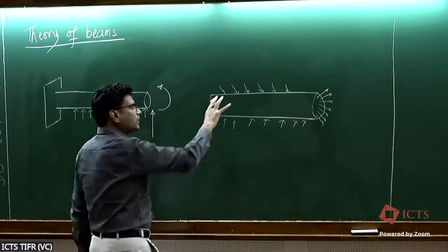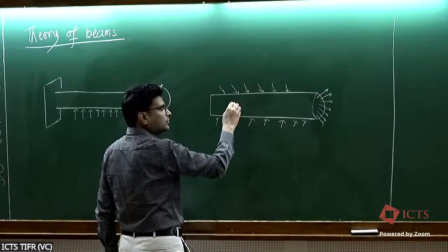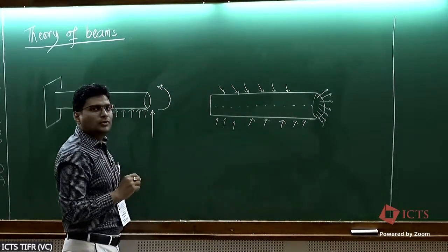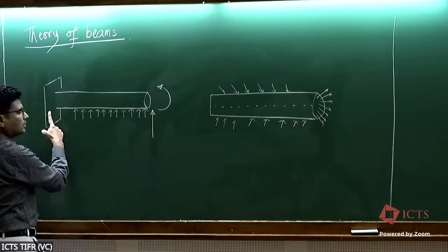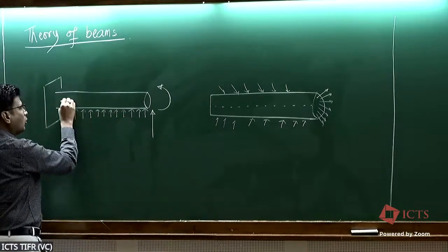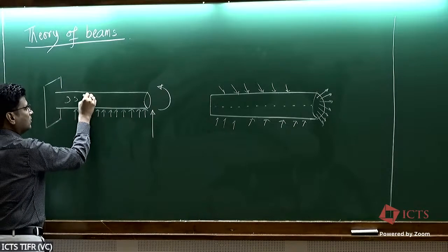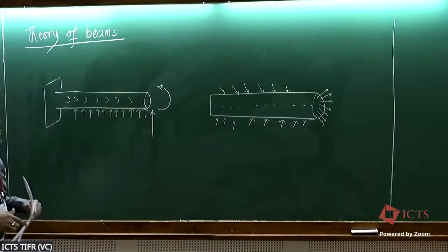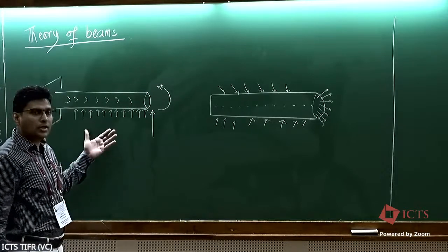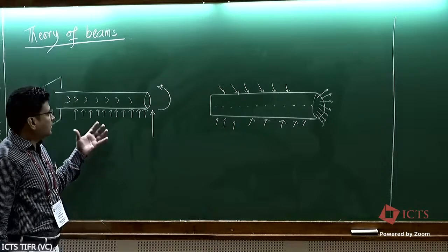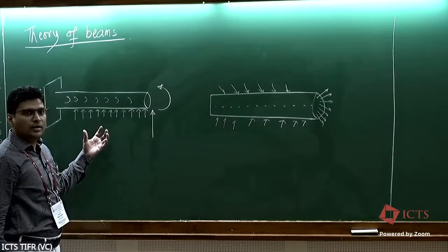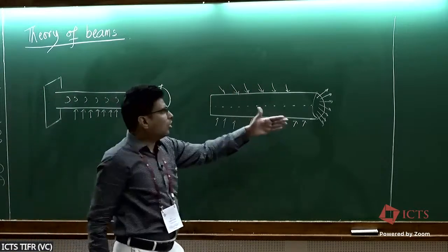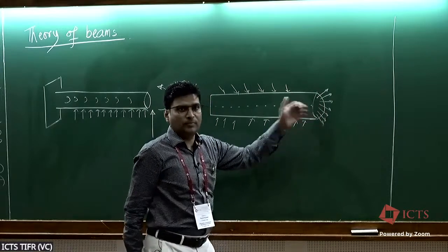And when you transfer these tractions to the center line, it's going to generate an equivalent distributed load and also couple. So at least the external loading that we see here is a statically equivalent description of a more general distribution over the surface of the body or over the cross-section of the beam.